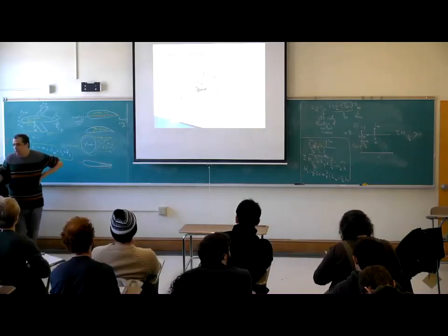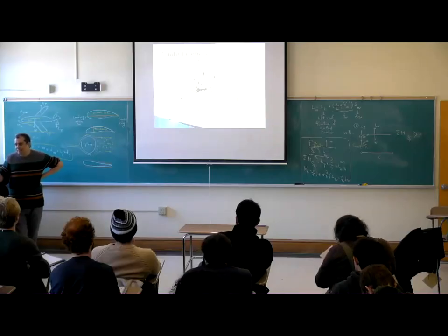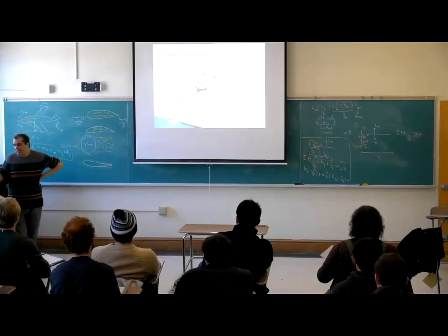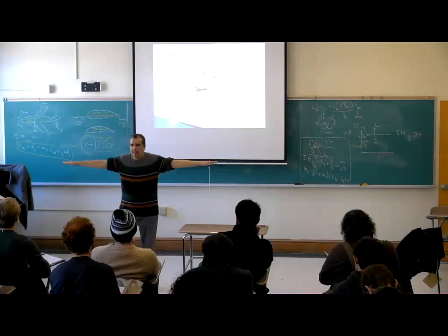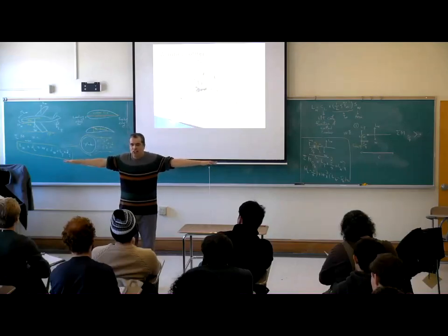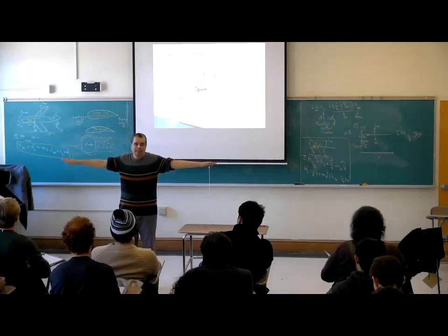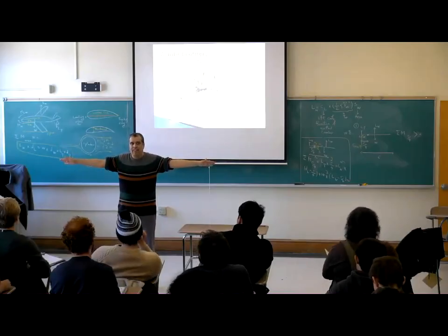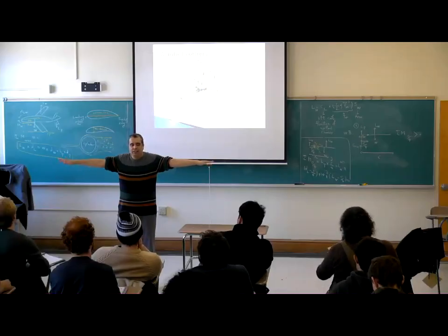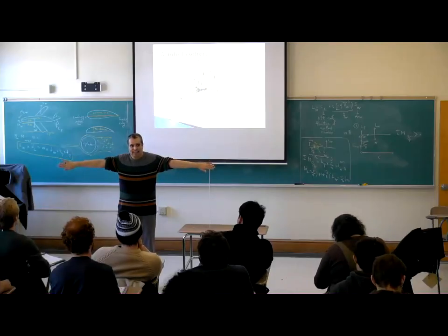So the Wright brothers, in order to control their airplane, used this tail. Take a look here at my hand, these are the tail. If I want more lift from the tail, I turn my hand this way. I have more angle of attack. If I want negative lift, I make my hand this way.